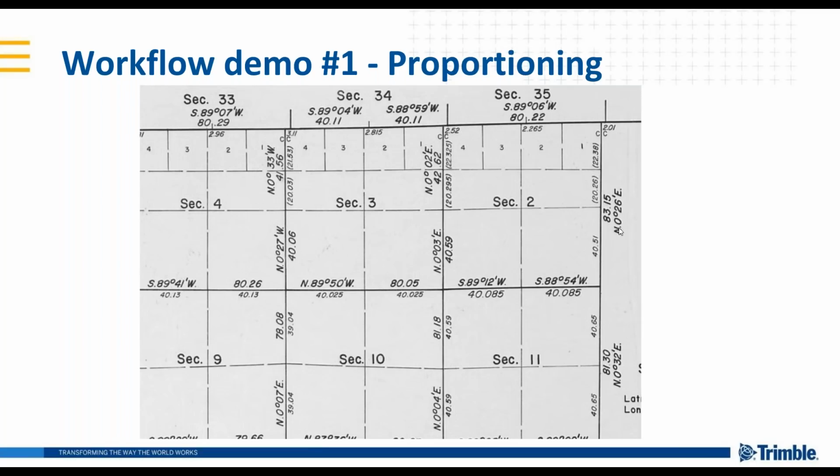This is a little bit more zoomed in. These give our azimuths or bearings. In this case, bearings. It's the United States plan, and our lengths are in chains. One chain is 66 U.S. survey feet. That is how the Public Land Survey System was surveyed originally, and consequently, that's how all the plans are. Excellent. Let's get into it, shall we?